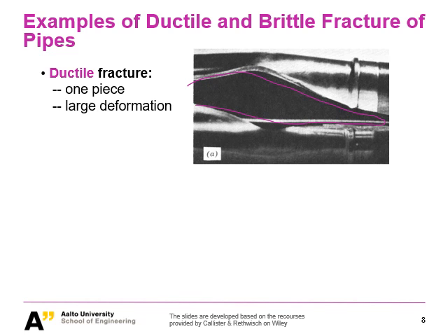You can imagine what makes a bomb dangerous, because after it explodes, it develops all the small pieces, and each of those small pieces is acting as a bullet. So that's why a ductile fracture is a good mode, having one piece, or let's say generally one piece. The second feature you notice is it has a very large deformation. These curvatures indicate this kind of large deformation, and obviously they are ductile, they're plastic.